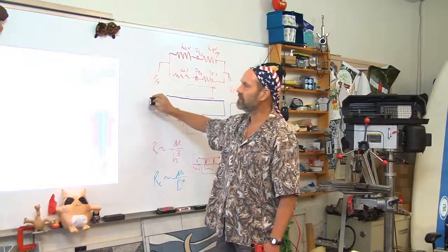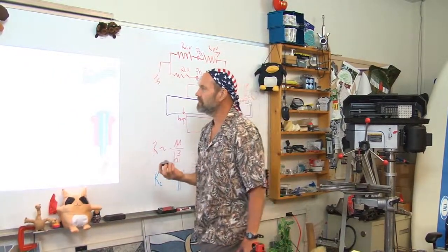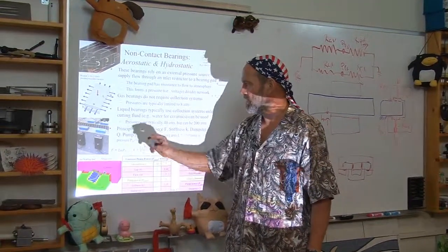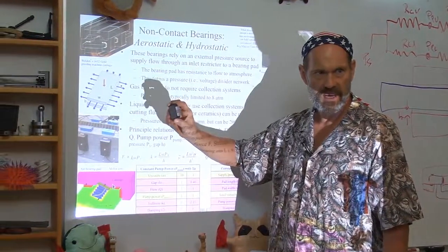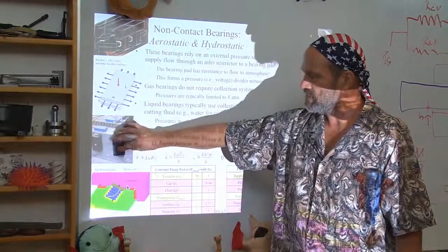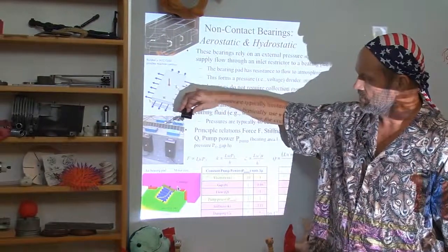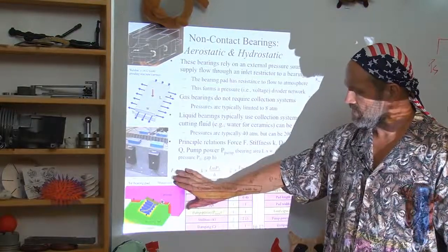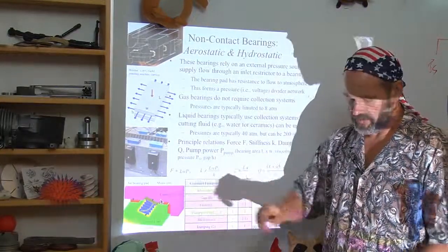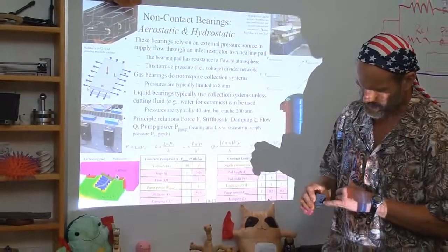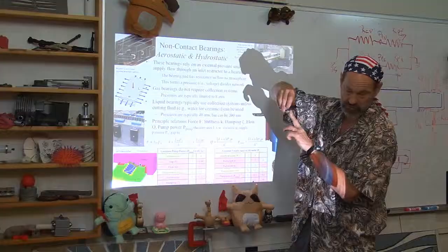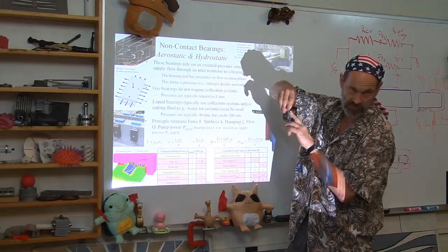Think air hockey table. This being a modular element, as we show here, for example, you can take these and instead of applying air pressure, apply suction and stick them to your structure, bring your carriage around them, position it with respect to the structure, and then either they're mounted and adjusted with a screw thread with these tilting pads by virtue of a screw thread and then a ball end on that screw.